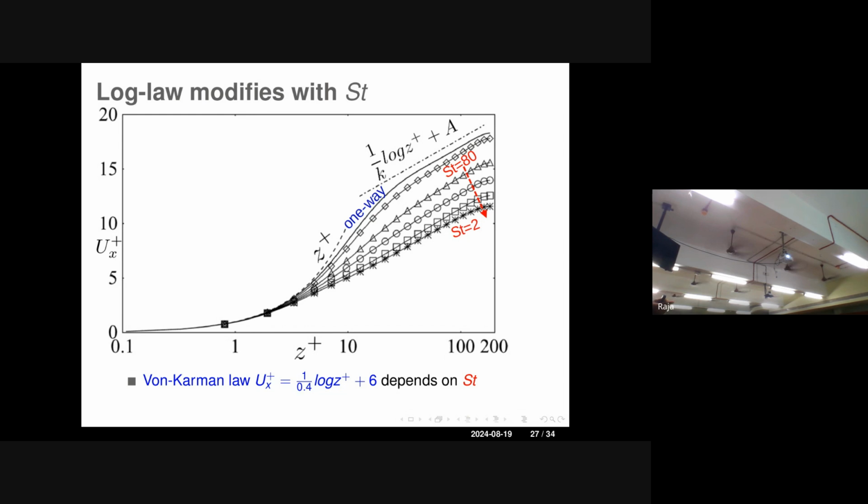And the other time scale really comes via your fluctuations. But this time scale, again, is not a sacrosanct time scale; it is a friction-based time scale that we are using. When you have large scale history, the time scales are different. When you have intermittent events coming out and so on, the time scale is different. But this is a wall friction-based average engagement.